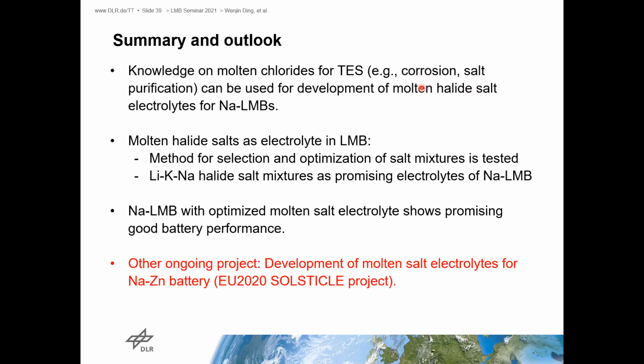So, molten halide salts as electrolytes in liquid metal batteries. We have developed a method for the selection and optimization of the salt mixtures, and it has been tested and published. The lithium, potassium, and sodium halide salt mixtures are found to be promising electrolytes for the sodium liquid metal batteries.